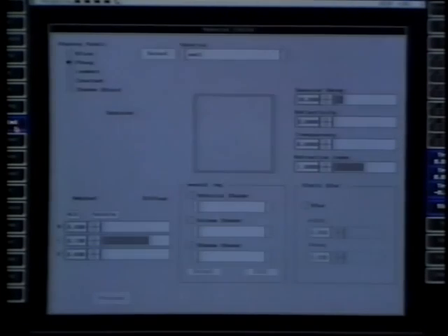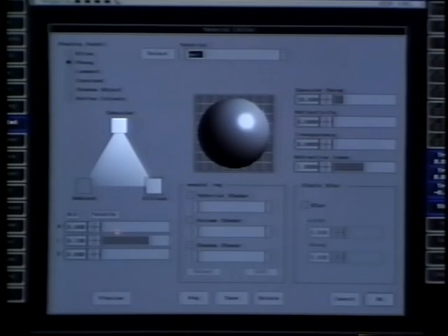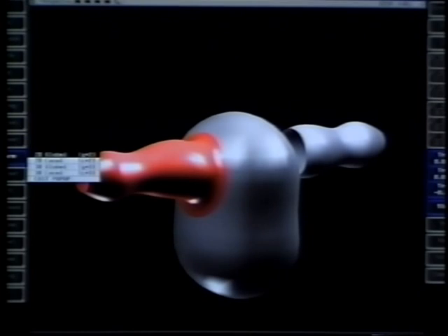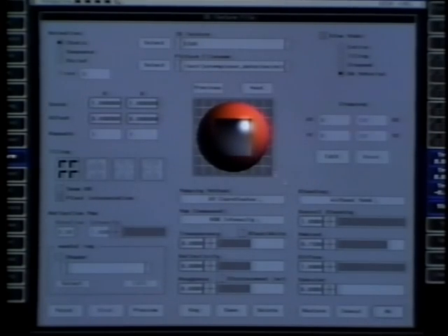Now we'll give the arm a material and make the material red. There is still a bit of a seam to kill where the arm hits the body. We'll fix this with a 2D texture and call up a gradient pattern. This will be a UV map, and we don't need to affect the diffuse or ambient values, only the transparency.